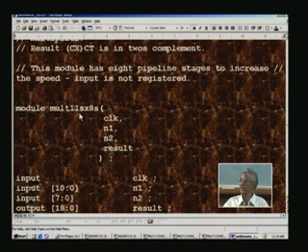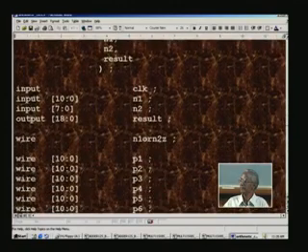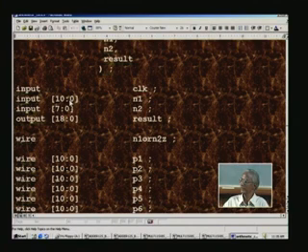This is the module name that we declare here: module multiplier 11 into 8, where S stands for signed. This is the design name we have given, implying that it is a signed 11-bit by 8-bit multiplier. We have the clock as an input, then the two numbers n1 and n2 as inputs, and the final result is also listed here. All the IOs are listed with their bit widths: n1 is 11 bits, n2 is 8 bits, and the final result is 19 bits.